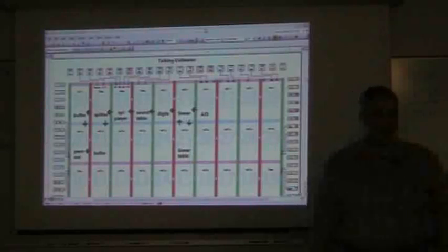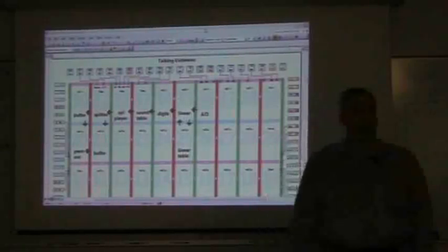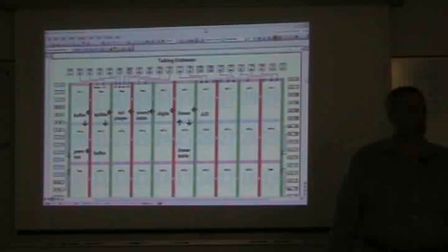The difference is our linearizer in the software is flexible, can be calibrated. The hardware, you did it once, calibrate once. If the manufacturing changes, you don't change your linearizer.